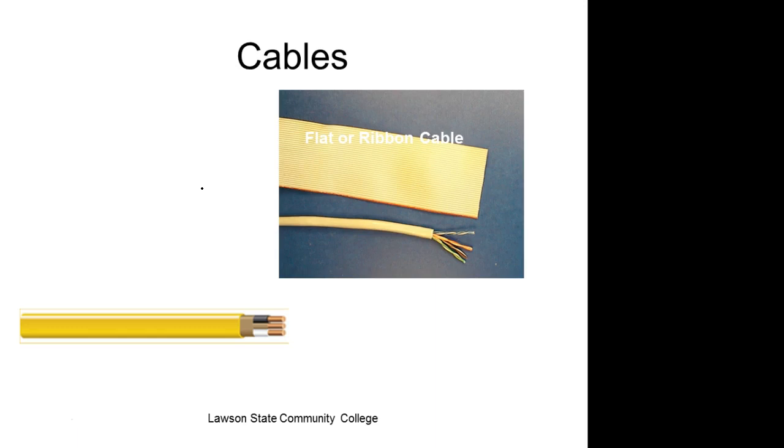If this wire came in touch with that ground, you'd have a short. If this comes in contact with the neutral, you have a short. This guy is not supposed to handle current. Okay, you understand? This wire is. So they call this the ground. So NEC does not call that neutral. They call it the grounded current carrying conductor. And the black wire, they call it the ungrounded current carrying conductor.